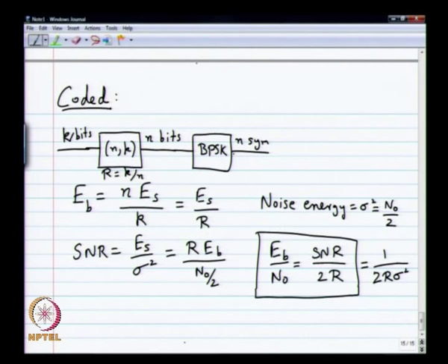In most cases when you do coded modulation, you will not be able to get analytical expressions for the probability of error. First of all, there will be two different probabilities of error. So, let me also talk about that. Suppose this goes through a channel, a noise is getting added, and then you do a decoder. If your code word is C, you get some kind of C hat here.